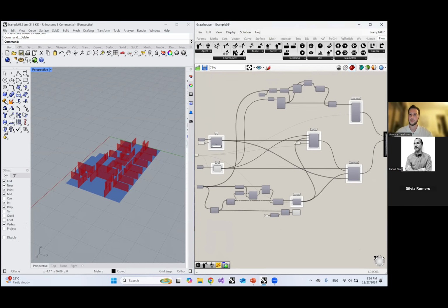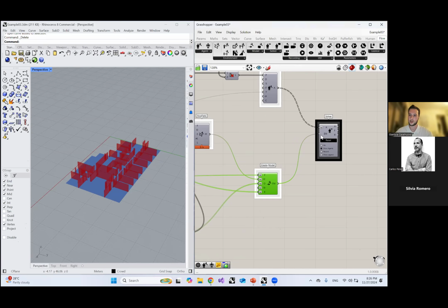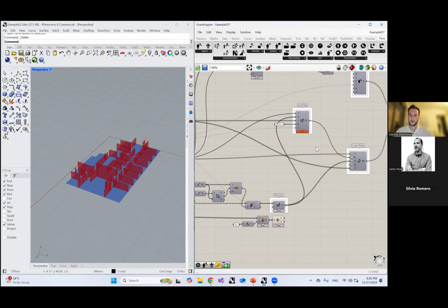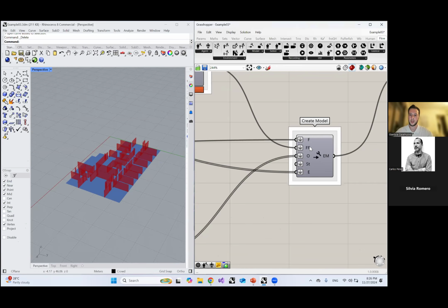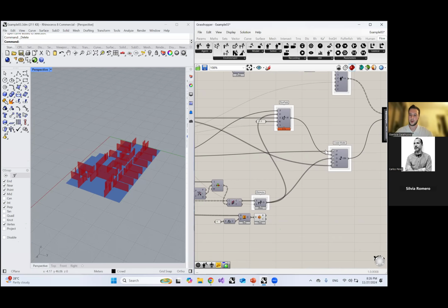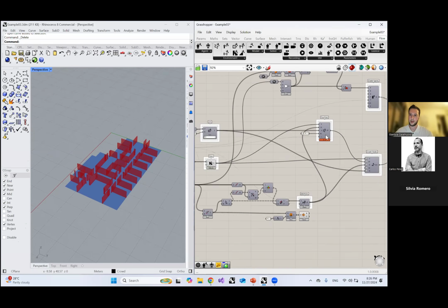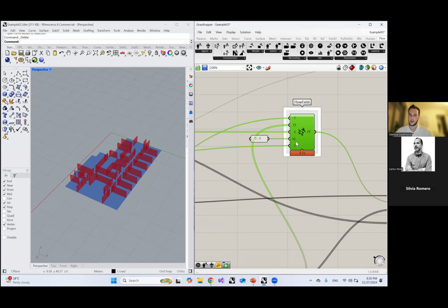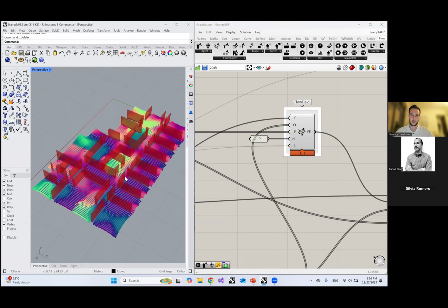As I said before, the solver takes as input two different parameters, the agents and the evacuation model. This evacuation model can be generated, and the minimum inputs that you can use are the floor, the exit and the flow field. The obstacles are optional, as are the stairs. And then the flow field is also created by a floor parameter, exit, and a label.